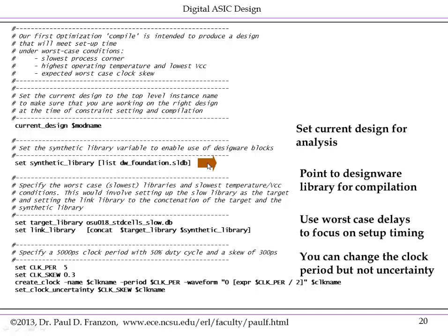Set synthetic_library. Things such as adders and multipliers and comparators are obviously not logic gates. They are collections of logic gates designed to perform a function. Synopsys has fortunately provided you with these designs in what's called DesignWare, and this refers to the DesignWare files that contain those. In this particular example, it actually needs the adder from that synthetic library.